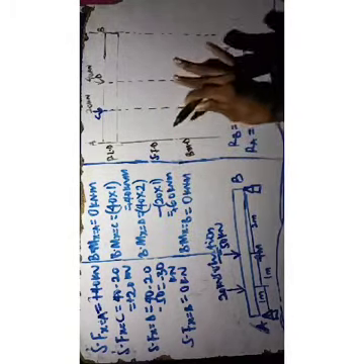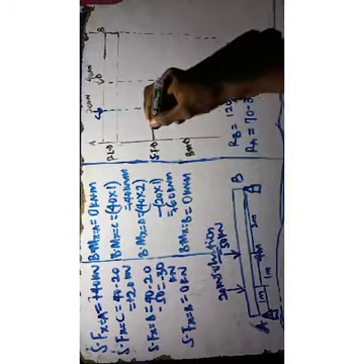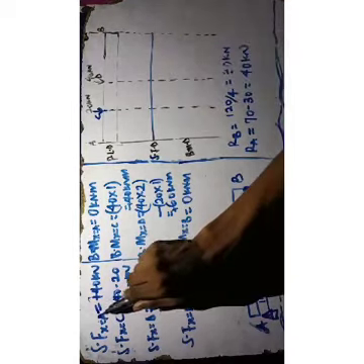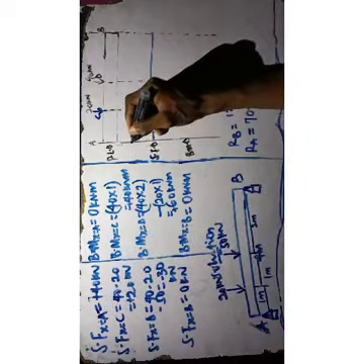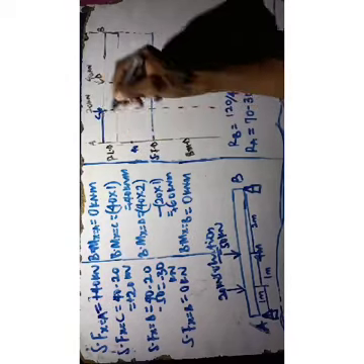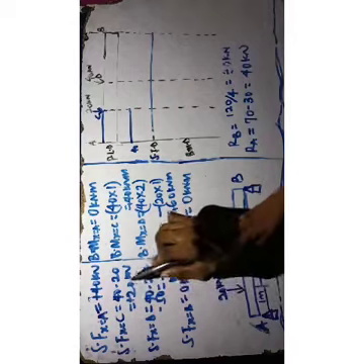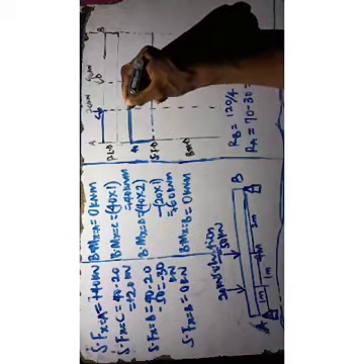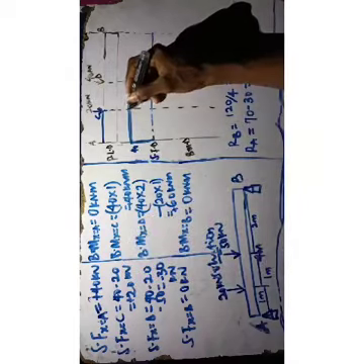Now from the question, the shear force diagram is, you draw the neutrality line, then that is at 0 for the shear force diagram. Then at point A, you have it as plus 40, so you go up 40. From 40 it goes in a straight line, it's constant, then it drops by 20. So at point C it is 20. So it drops half to 20.